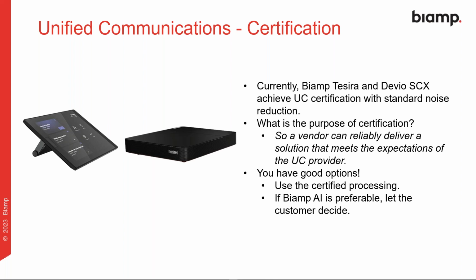One thing I will say is handoff is something that is often discussed, and what that means is when you connect a certified endpoint like a Biamp Tessera DSP to a UC system, if you've met certification, traditionally we've always expected that the AEC would be disabled and noise reduction would be disabled in the UC system.